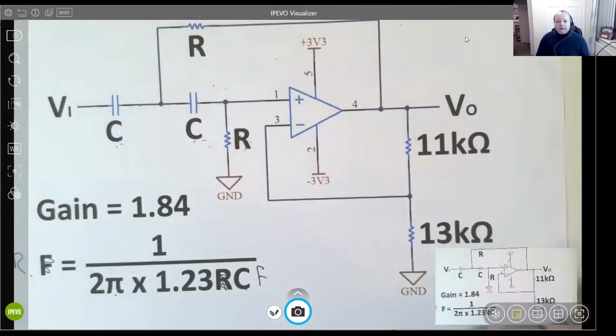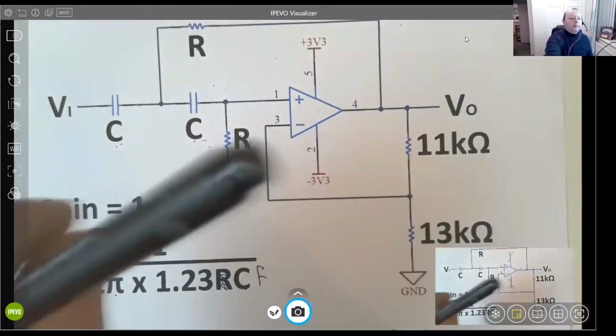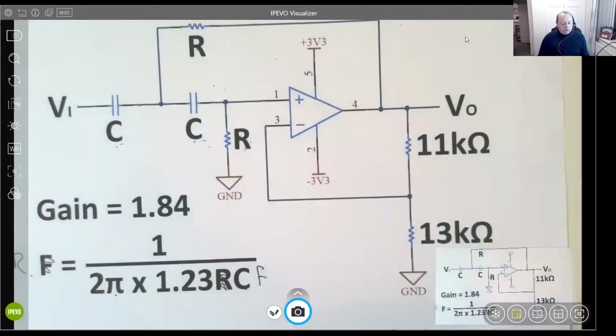So the way I do it is I usually start off like this amplifier here. This is just my starting point, I'm sure everyone's different. I usually start off with the resistor here, the bottom one, with 10 kilo ohms. It's an arbitrary value, because it's between 1 kilo ohm and 100 kilo ohms, and I'm usually looking to keep my values in that range.